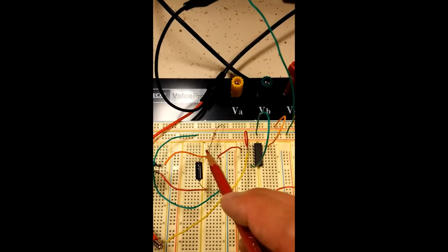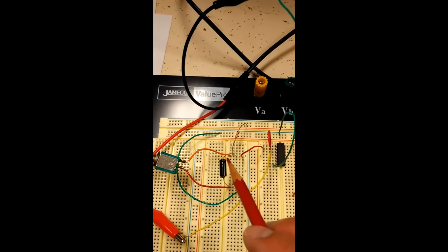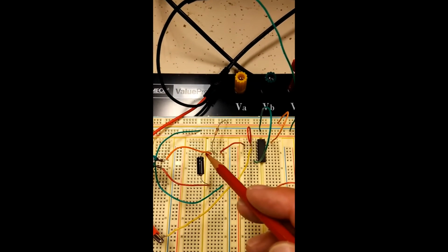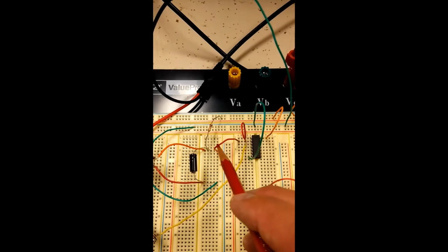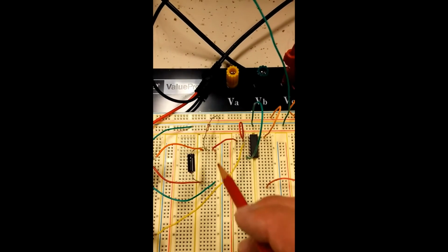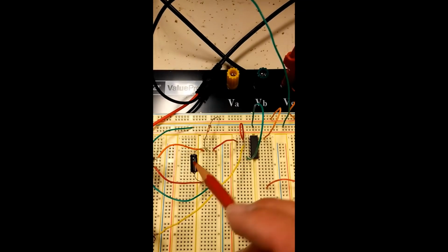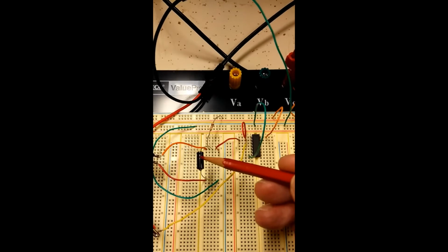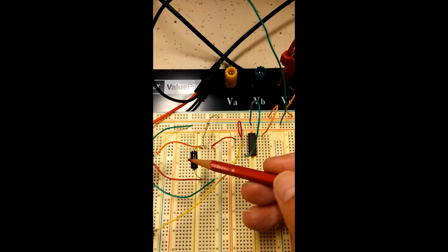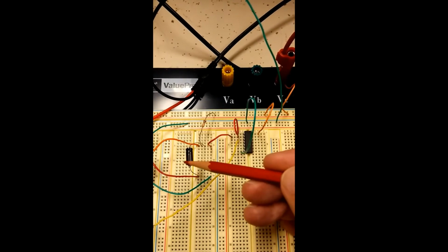If the switch is not turned on, that means open circuit, and you have the voltage drop between this junction and the ground. You're going to have 5 volts because the capacitor is a high resistance, like an open circuit for the DC circuit.